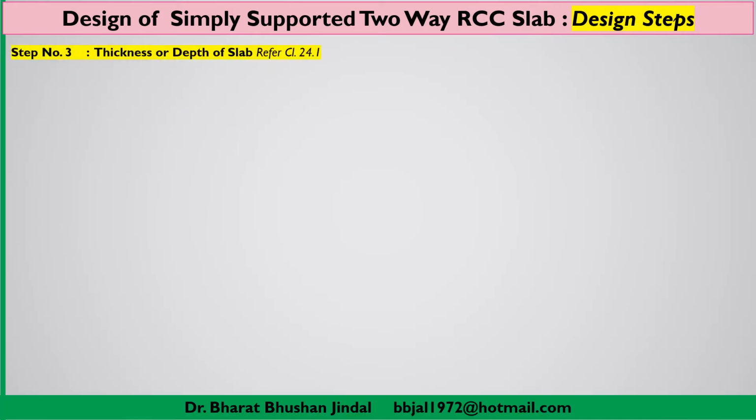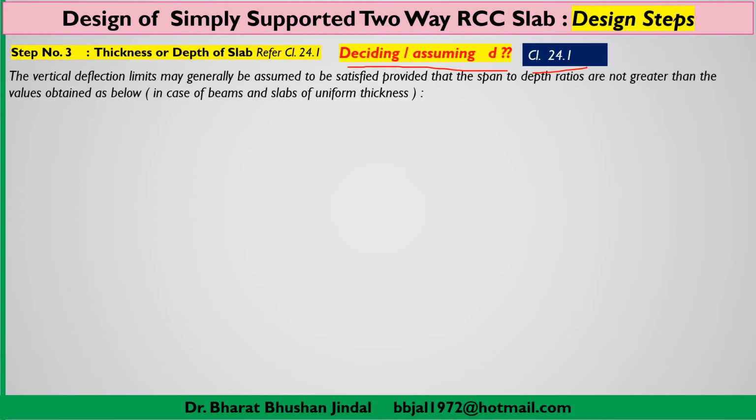Now in continuation to step number 3, where we have discussed the thickness of slab, a very important part of this step is how to decide what should be the effective depth of the slab, and we can refer clause number 24.1. And based on this value which we will assume for effective depth, we can later on calculate the overall depth of the slab.